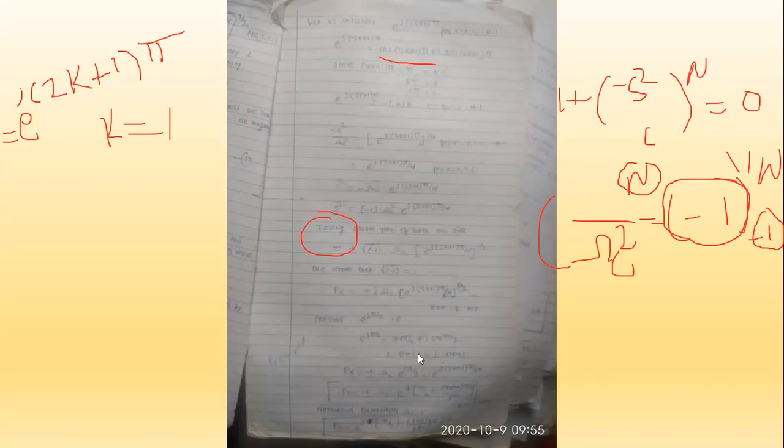Cos of pi by 2 is 0, minus j, it is the j. So shall I substitute e raised to j pi instead of this j? When I substitute e raised to j pi instead of this imaginary value, the equation becomes this. So pk, that is the poles of the equation, is plus minus cutoff frequency times e raised to pi by 2 into e raised to (2k plus 1) pi by 2n.